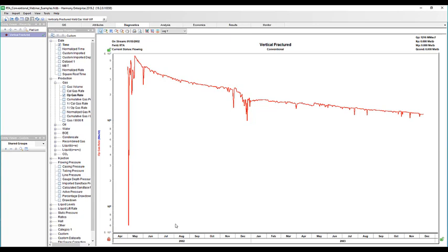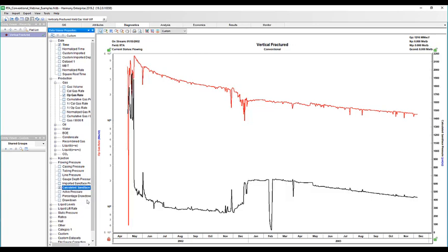When I take a look at my diagnostics, we can see that I have applied my gas rate here. We have around 2 years of production history, and we can see that the gas rate dropped and then kept producing, so it continued to produce. Now we can also apply our surface flowing pressures on the diagnostics plot. And when I do that, we can see that perhaps a pressure increase in the pipeline caused a back pressure to occur and that rate to drop by a little bit. Now, your daily production history is typically all that's needed for this kind of work.